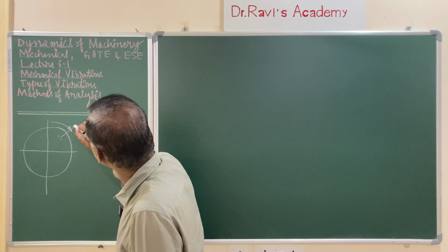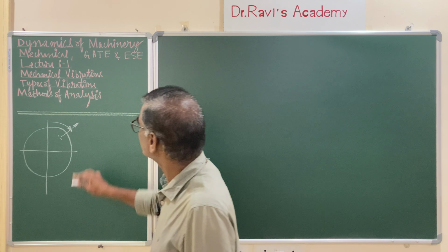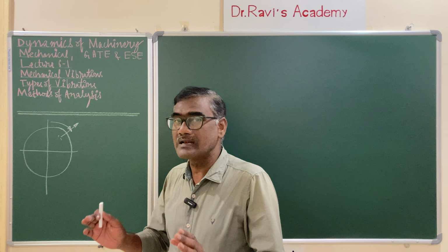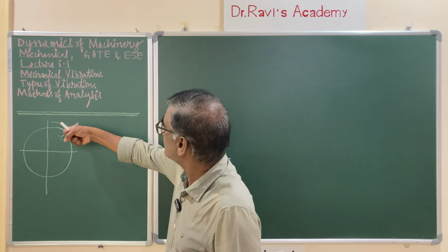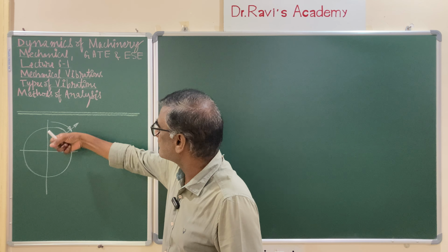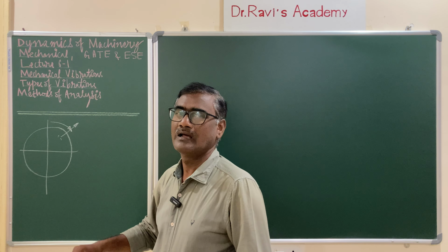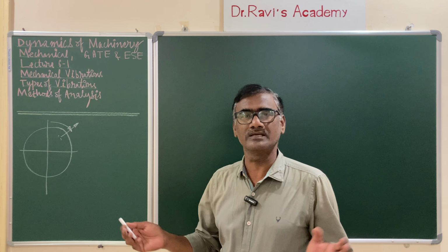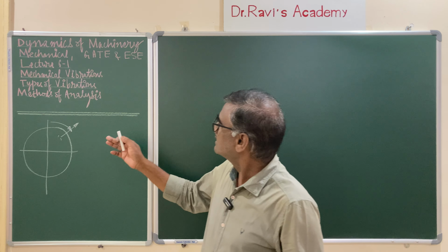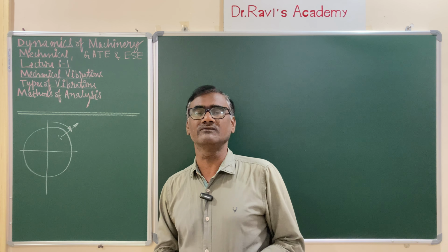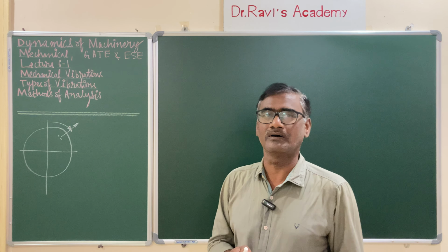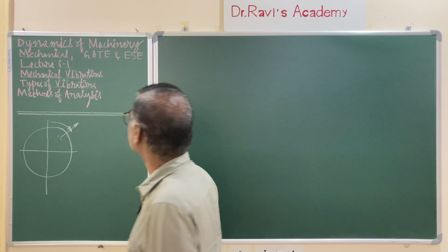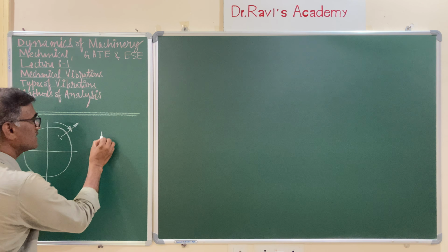Obviously, what happens is when it is rotating with very high speed, this leads to centrifugal force, unbalanced centrifugal forces. So these unbalanced centrifugal forces pull the material away from the center of rotation, and that leads to the vibration. So it's not possible to eliminate the vibrations from the mechanical or dynamic systems. You can only analyze it and reduce the severity of the vibrations by means of various methods of balancing of the machinery. So this is exactly the definition.